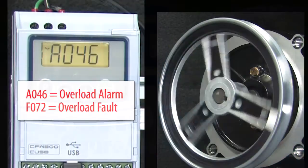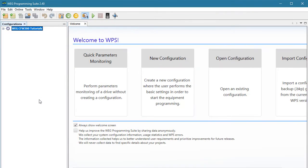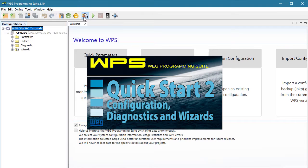Getting an overload fault or alarm can be frustrating, but once you understand what's going on, getting it fixed is pretty straightforward. And the good news is, the free WEG programming software makes it super easy to visualize everything you need to know about overloads. I've already created a configuration and a resource, and I'm connected to the drive. Check out the WPS Quick Start video to learn how to do all of that.